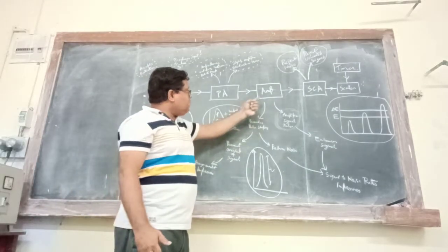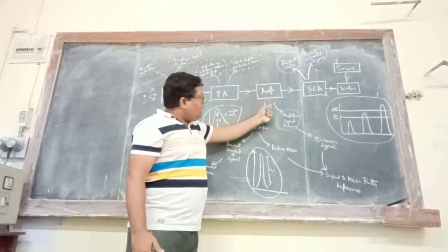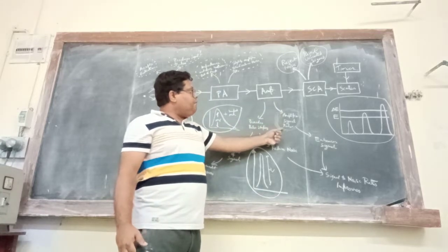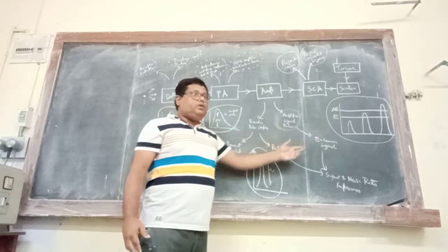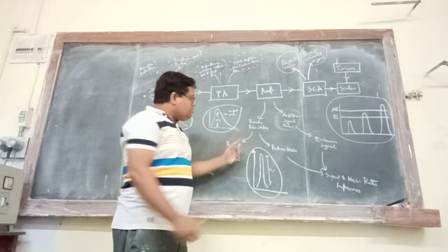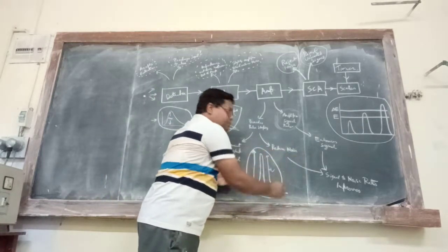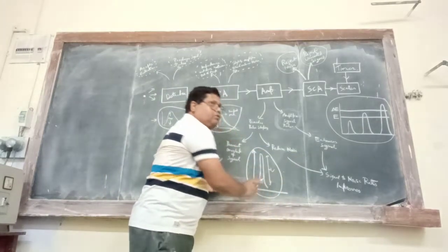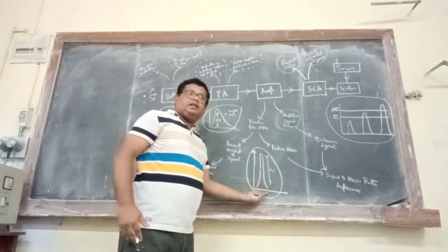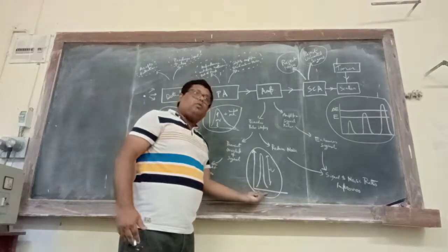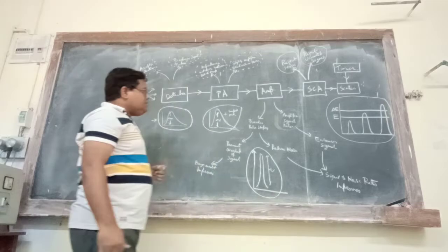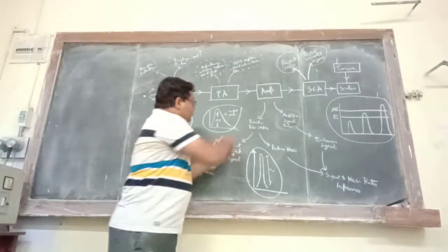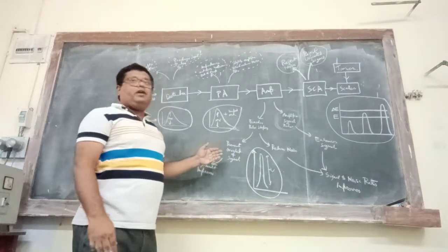Now here, what happens is that along with the signal amplification, which enhances the pulse, this also shapes the pulse. That means the tail part is now gone. It is a symmetric pulse. Now what's the advantage? The advantage is that this will prevent an overlap of signals.